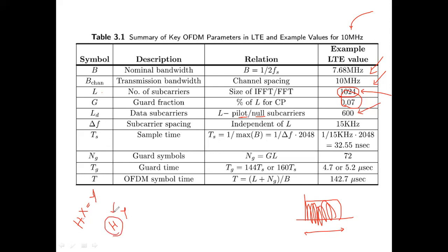The way to know the channel frequency response, or so-called channel state information, or channel impulse response, is this. The trick is that for every 100 symbols or every 1000 symbols, you put a known sequence called a pilot in between. From this pilot, you know what you have sent, and there is a channel which is constant for at least a certain period.